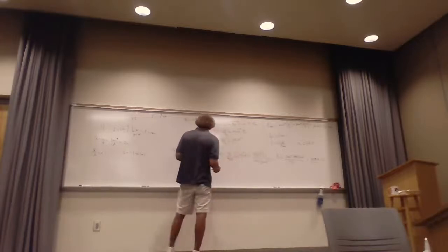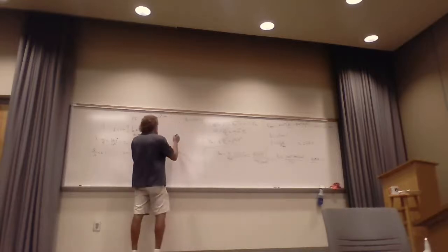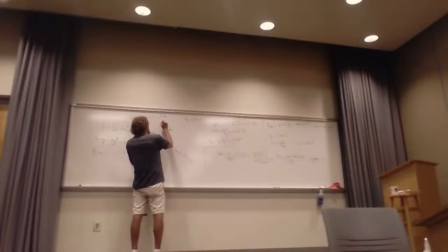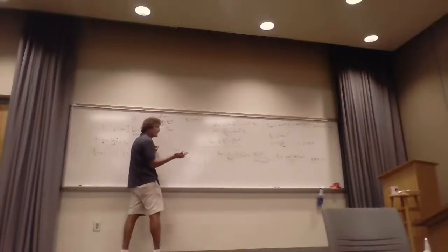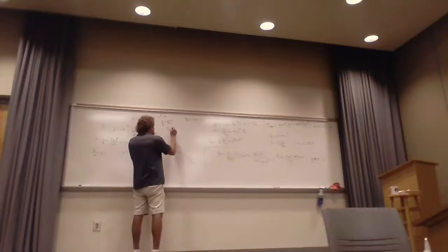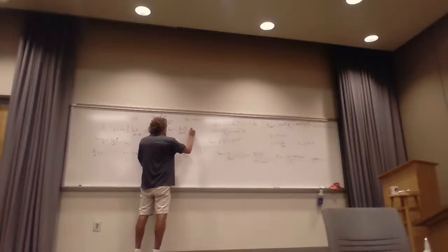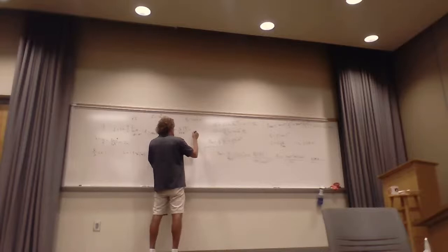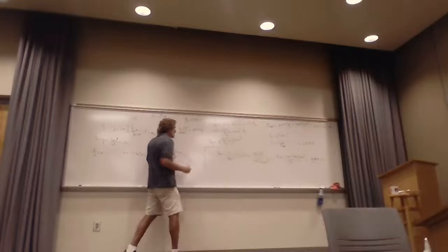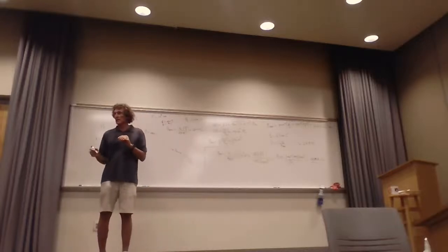Or you can just do the calculation for the last part when they want the average power right here. And they want this at R equals 4,000, right? Theta equals 90 degrees. Well, the sine of 90 is 1, and therefore this is just equal to total transmitted power over 4 pi R squared, and here it's 3/2. It will be twice the actual power at 45 degrees, or it's going to be 60 microwatts per meter squared if you look, right? And that was the first problem.